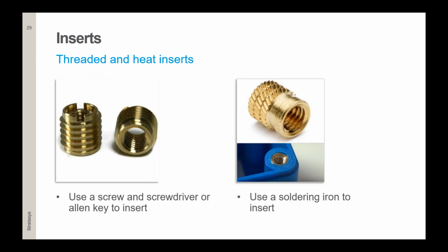Okay, thank you. And then we got another question from the audience: how can you insert a pause during the printing in order to put the nut inside the part? That's a very good question. Actually, I'm planning to show this in our third session when we go into the example of GrabCAD Print, and I will show you how to insert a pause. It's just a two-click thing, and it's quite easy.